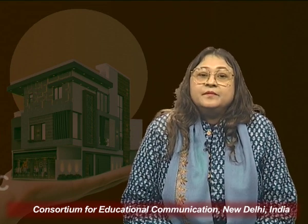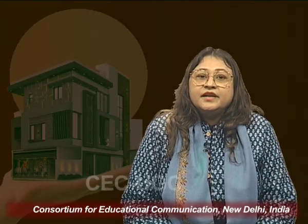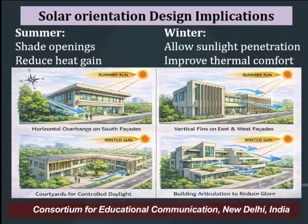Solar orientation also has a lot of design implications, like discussed. In summer the shade or the openings will reduce the heat, and in winters the sunlight can be allowed to improve the overall thermal comfort of the building. Like you see on the screen right now, there are buildings which have overhangs. The overhangs will not allow the sun to come inside because of the projection, and yes, the sun is at a higher altitude.